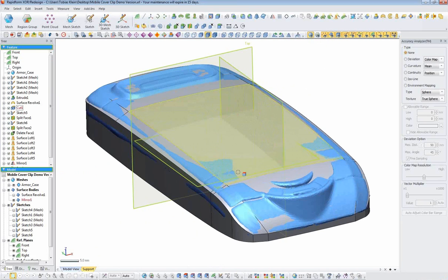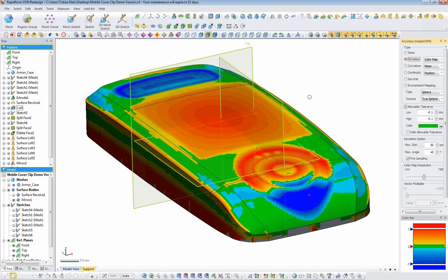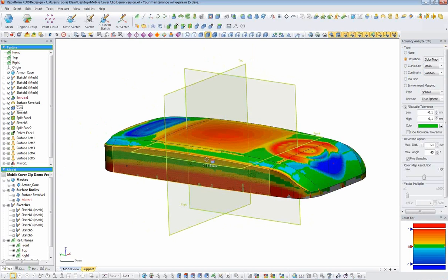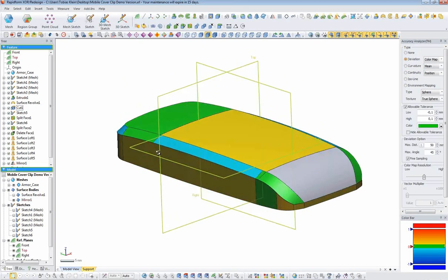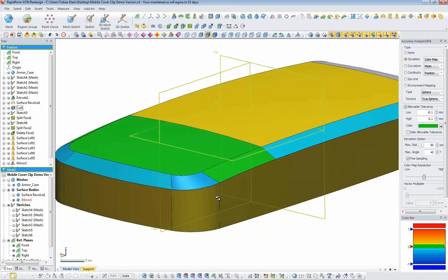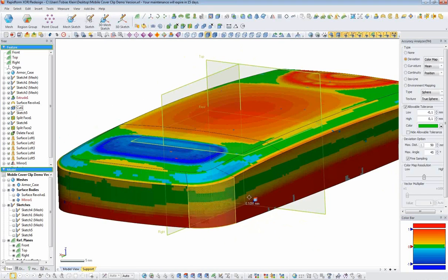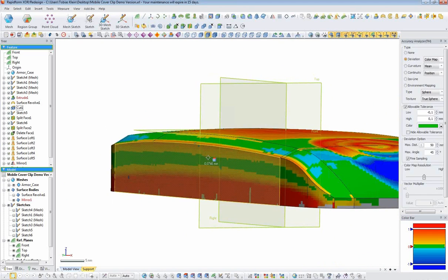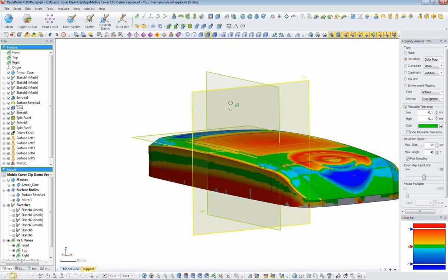So this is basically what we did to get the rough outer surface of this model, and we still have several blue and red areas, and we can still tweak something, because this is not yet very accurate. We can, for example, do some drafting around here, so we can insert a new line around here and then just fold a part of the surface to the inner side so that it drafts in. I will use that drafting as well from the center plane. It's basically the same as we did before.